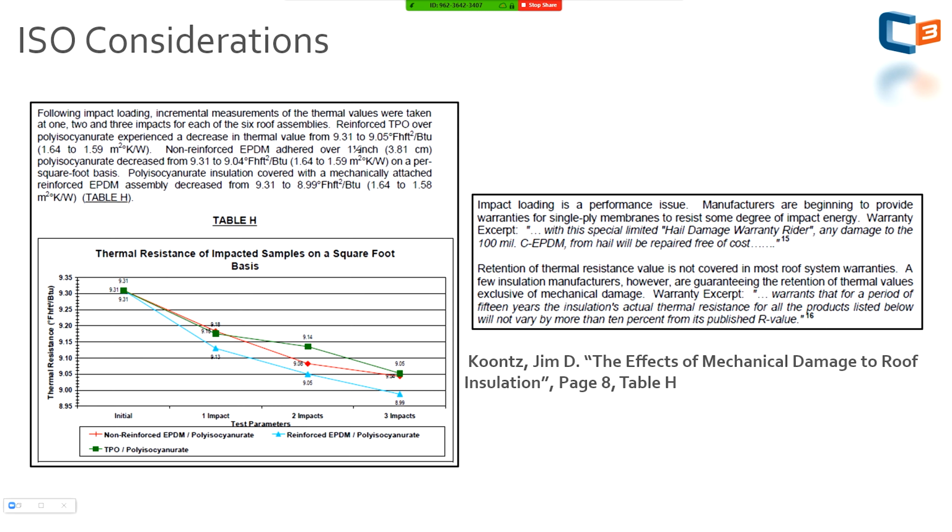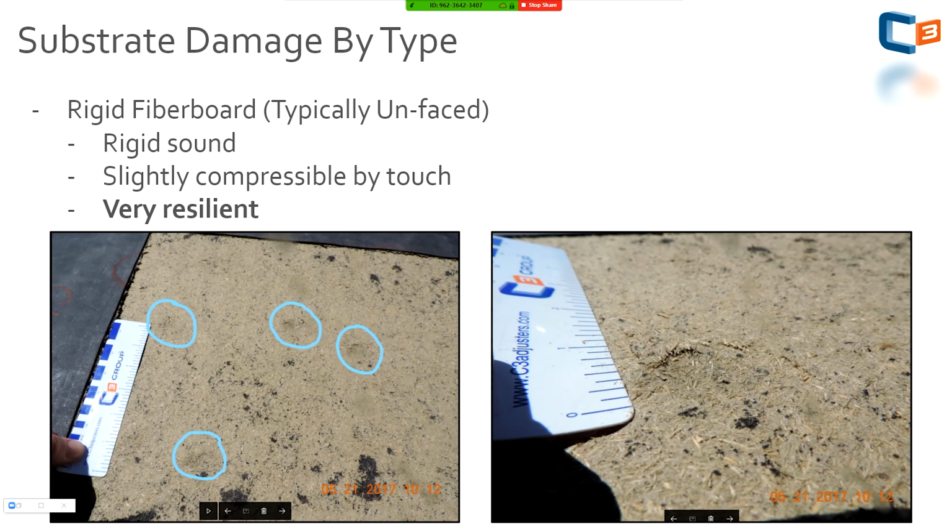My recommendation here, if you really want to quantify R value loss and how important that is, think of a mall's energy bills. Let's say the lifespan of the roof is 30 years, and you have 30 years of energy bills, whether it be heating or cooling, and you add all that together, and you take 2 or 3 or 4 or 8% of that figure. That is a huge loss. So quantify it in means that people can easily understand. It's easy to look at this graph and say, that's trivial, but just try to quantify that in different ways, and it's pretty successful if you do.